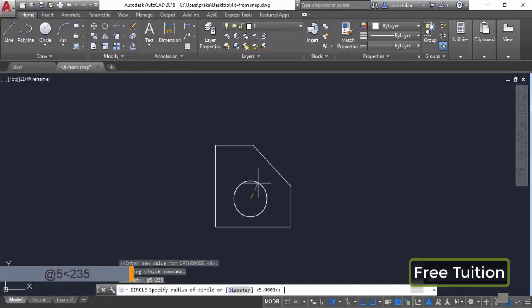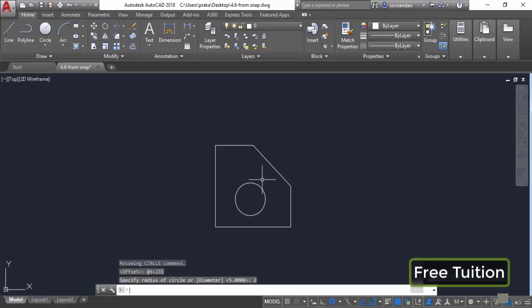So now the distance is 5 and we need to enter the angle, which is 235 in this case. Now press enter and we have our midpoint. Now only we need to enter the radius, which is 2 in this case. Press enter. Here we have the geometry. So without taking any reference of any line or any other geometry, we can make these kind of geometries quite quickly using the from snap tool.